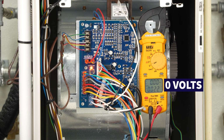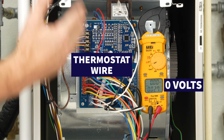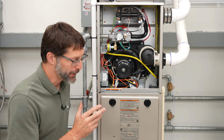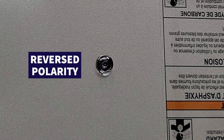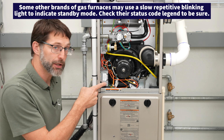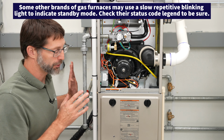So that means that your problem would be in your thermostat wire, if you are trying to turn the heat on and nothing's happening and you're not getting a signal to turn on. On a Carrier, Bryant, and Payne furnace, a rapid LED flashing light means that the polarity is reversed. So the hot and common are switched, either at the circuit board, right here at the electrical connection, or at the power supply to the furnace. So make sure to turn the power off in order to correct that problem.